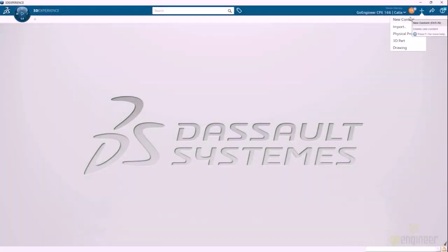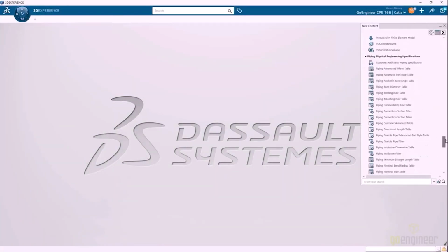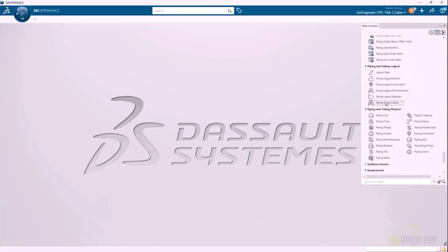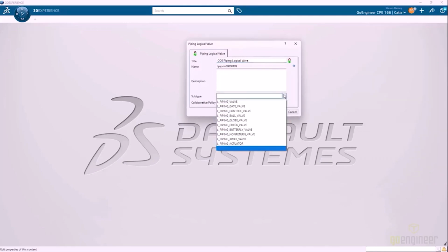So next we'll be making a piping logical valve. So let's scroll down and select on that. So we'll rename that. And we'll give it a subtype. So I'll drop that down. So it's again coming from the table.